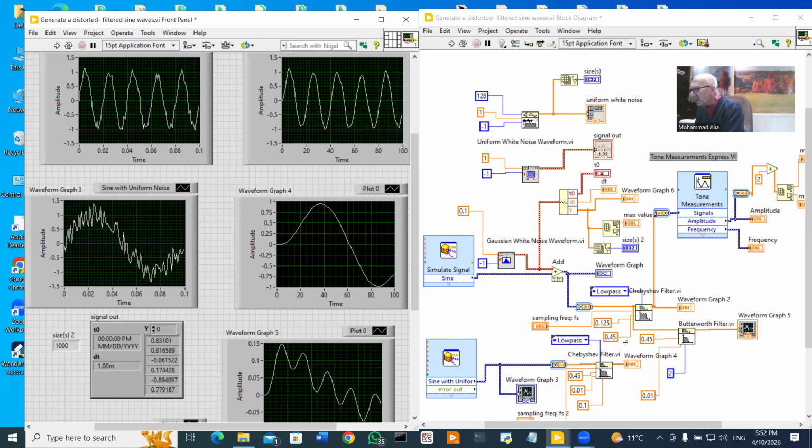If you look at them, you can see that the high frequency side of the Chebyshev filter is very sharp compared with that of the Butterworth. And you can see the band pass level is practically constant for the Butterworth filter, but the output of the Chebyshev filter allows some level of ripple noise. Anyhow, we shall demonstrate both of them.